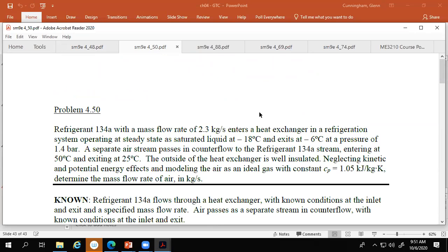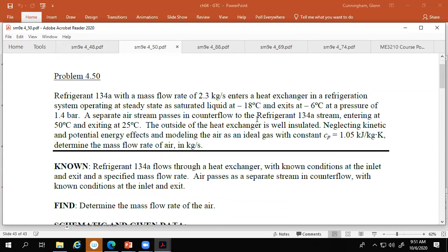So let's take a look at this one. Ah, yes, a little refrigerant. And we want to be sure that we continue to work in the tables. We have steam tables, we have refrigerant tables, we have ammonia tables. Whatever tables are back there, they all work the same way in terms of the saturation dome and all that sort of thing. You draw the same pictures, the same isobars, the same isotherms. We simply go to a different table to get the numbers, and they jump all over the place depending on what the substance is.